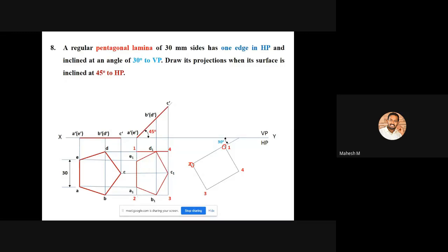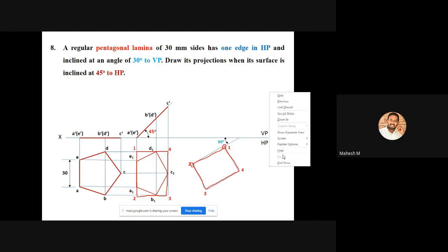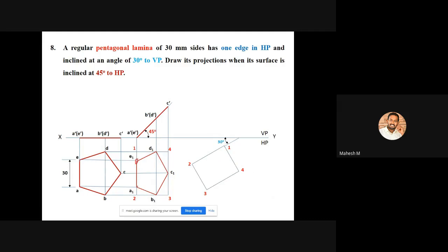Okay, so that is what exactly is marked here. You can create this imaginary rectangle. Now you can use your 2H pencil because it is not a component line. The component line is a pentagon. So you can draw this total square towards the 30 degree inclined profile. After creating this, you can mark all the 5 points. So what are all the 5 points? The points are E1, A1, B1, C1, and D1.